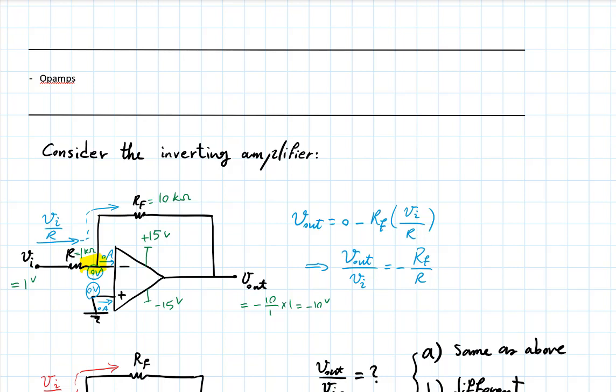If I drag down V out, the voltage of the negative node, the highlighted node, will actually just go down because of the way the resistors are connected. So there is an effect that counters the noise that had momentarily raised this voltage. So it stabilizes the circuit.